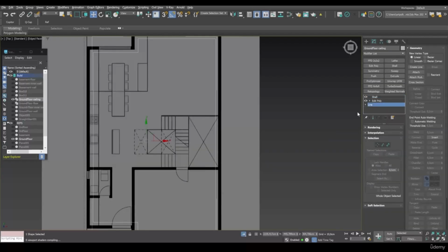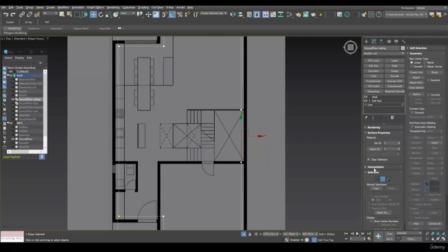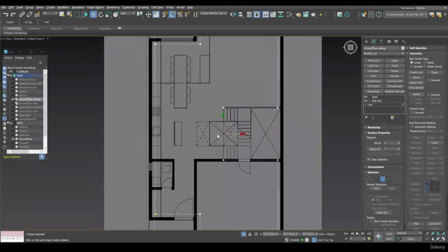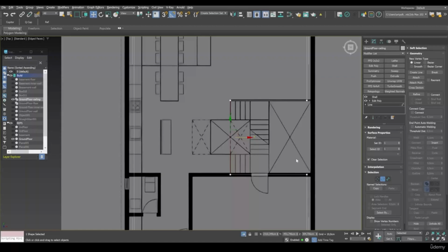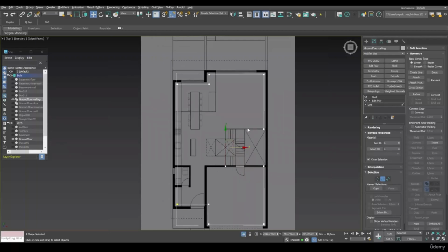And I go to the level of the line, and this is the space we'll modify. Set points in spline using the refine method. Select the edge, hold Shift, and stretch like this. Alright, the stairs will be located here in the center. There may be an elevator as designation on the plan, but we'll not detail the interior now because in these lessons we're working with exterior. However, we will add flights of stairs in the middle. So I'll make this space.